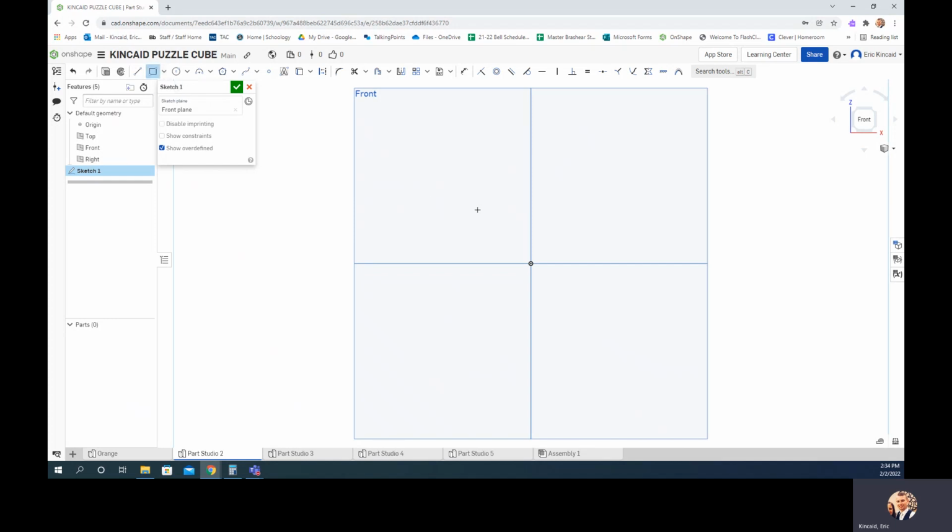There are many ways that you can create this part. If you want to do it a different way because you prefer that way, that is completely fine. But I'm going to create a rectangle that is my overall shape. So I'm going to do 2.25 wide, hit enter, and I'm going to make it 1.5 tall. Right, so that's my overall shape.